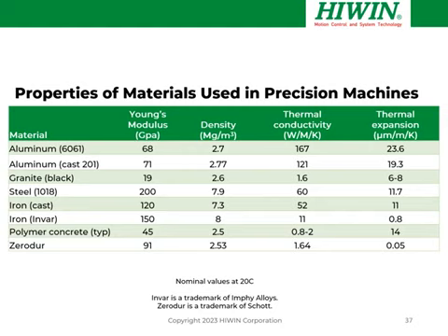There are some unique materials that are specially engineered for precision engineering. You'll notice a material called Invar or a material called Zerodur. The reason those are chosen is if you look on the far right-hand column, again, thermal expansion, look at how small that number is. Compare it to, say, aluminum and Zerodur, you get a huge difference. So if thermal expansion is an important characteristic, you've got a varying temperature, for example, you may want to consider using Zerodur, but it's not a very good structural material. It's actually a type of glass ceramic. So use materials judiciously, work with an experienced motion system supplier who can help identify which materials to use where and how they should be deployed in the motion system design.